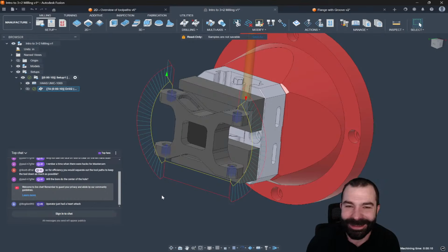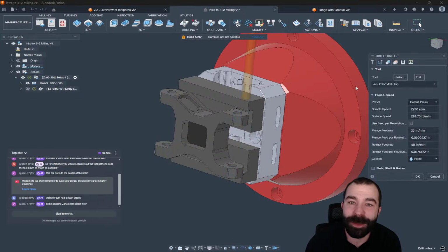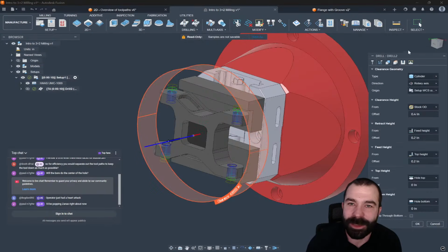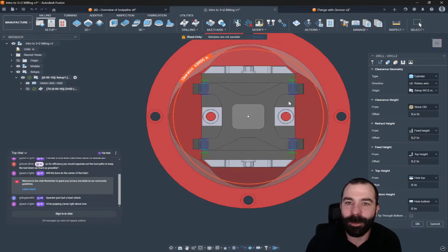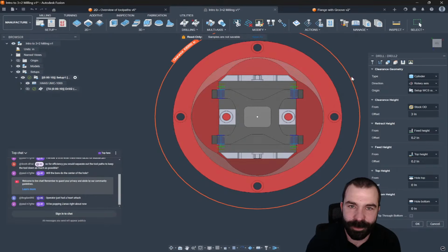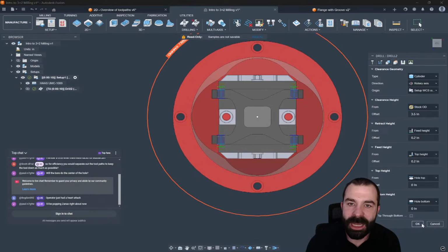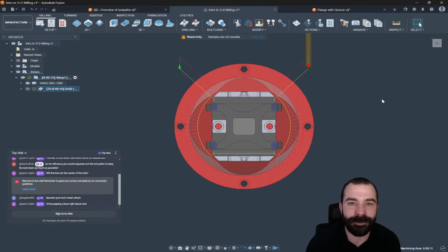Yeah, this is one of those scenarios, and this is why I felt that instead of going toolpath by toolpath, we're breaking down the tabs before we do that, because we do know that we can remedy this by going to our heights tab, and we do need to make those changes based on that. So some things that can happen is by changing our clearance height out further. As you notice, I'm grabbing that clearance and dragging it much further out, and we can hit OK and see if we get a different result. As you're noticing, we're coming from further out.